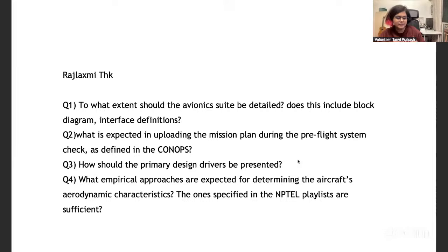When I say avionics, I mean the computing avionics, the sensors, as well as the power systems and any other electrical systems that you have on board, like motors, etc. You should also include any avionics which are specifically used for the engine and for deployment of the control surfaces, and also for the landing gear or whatever is your method of runway independence.